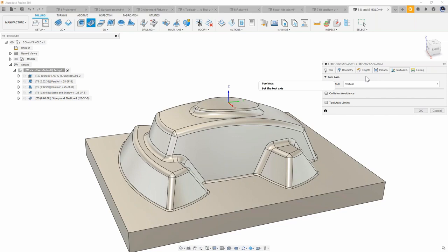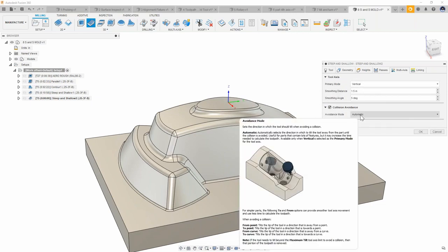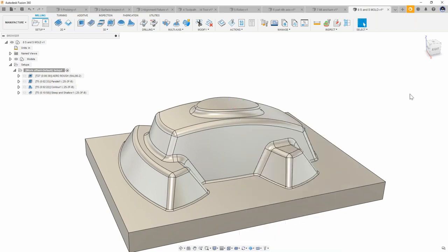And generally when we're doing something like that, we want it to be automatic. So we could just turn on collision avoidance here, and this is going to automatically convert a 3-axis toolpath into a 5-axis toolpath. So if I want to use a shorter holder or a shorter tool, I can really get the benefits out of my machine tool while maintaining rigidity and increasing my surface finish and my productivity. Because we've all probably run tools that were hanging out 4 or 5 inches and they probably didn't sound super great. So we had to slow it down, slow down the RPM, slow down the feed rate. This lets me put a short tool in there that's stubby, that's rigid, that allows me to cut fast and efficient and get those results done. Really the easiest way, just a simple checkbox. So let's look at an example for that.